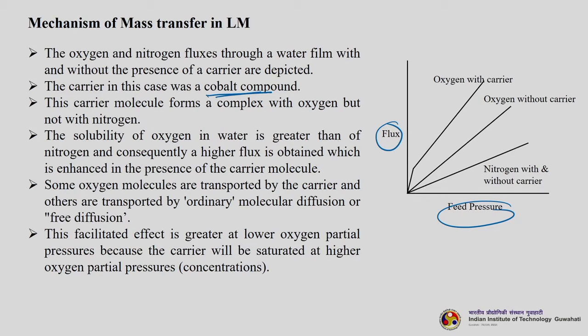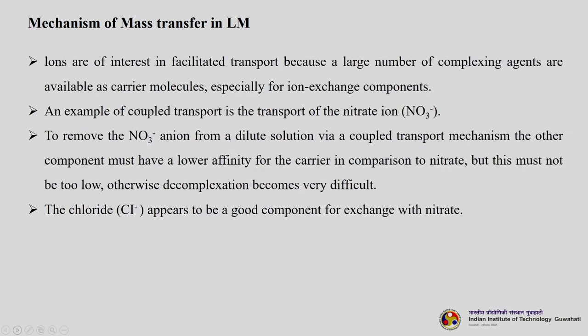Now, this facilitated effect is greater at lower oxygen partial pressures, because the carrier will be saturated at higher oxygen partial pressure or concentration. You can see the flux is high for oxygen with carrier compared to oxygen without a carrier, while nitrogen with and without carrier is the same, because nitrogen is not reacting with the carrier. So, this figure tells us the importance of specific carrier mediated transport. Ions are of interest in facilitated transport, because a large number of complexing agents are available as carrier molecules, especially for ion exchange components.